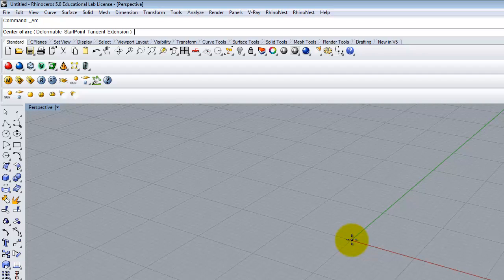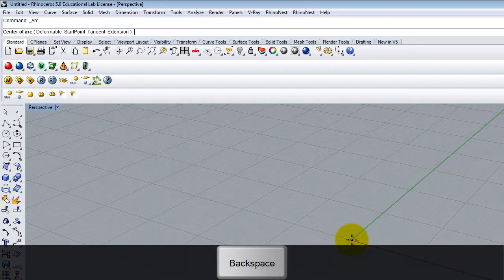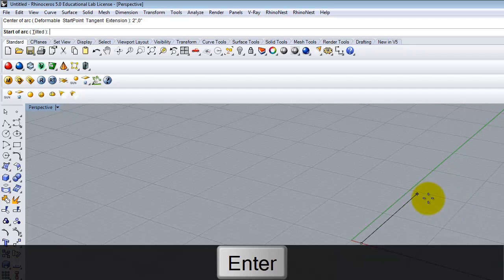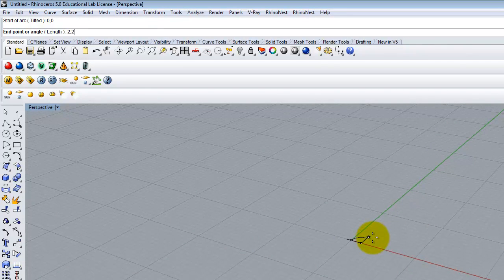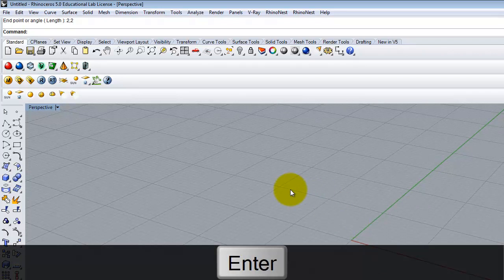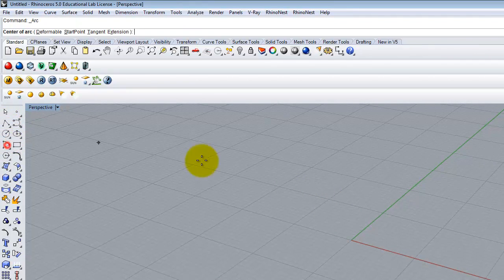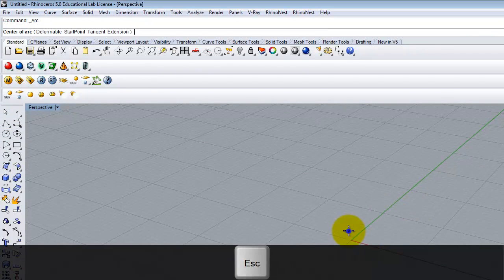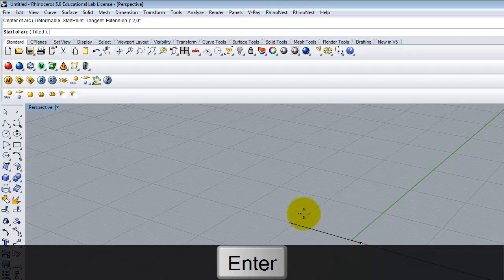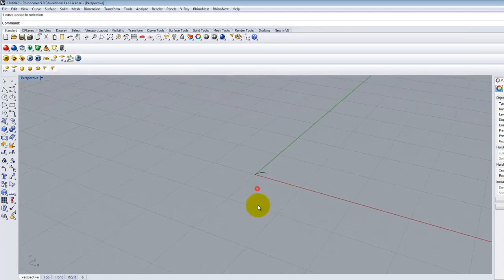So I can go ahead and type coordinates of 2 inches, comma 0 as my starting place, which would be the center of my arc. And then 0, 0 would be one end. And then we can see that I'm obviously going in this direction. And it would be 2, comma 2. You would think that I would have been able to do that, right? 0, 2 inches. 2, 0 there, and 0, 0. And I think it just wants a direction, yeah. So there's my first little curve.